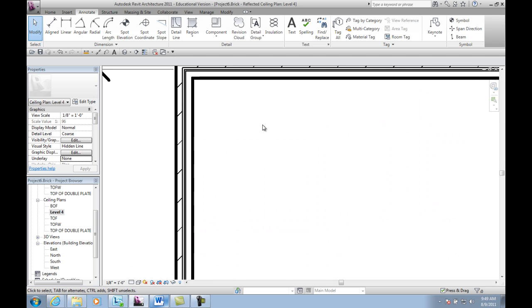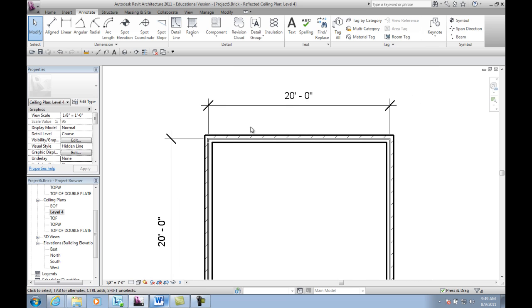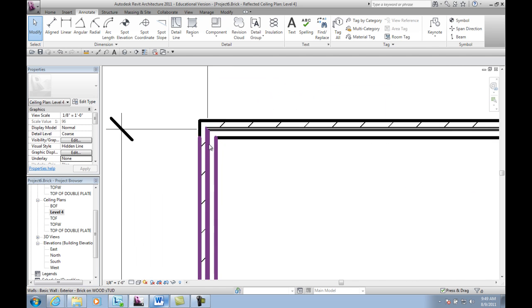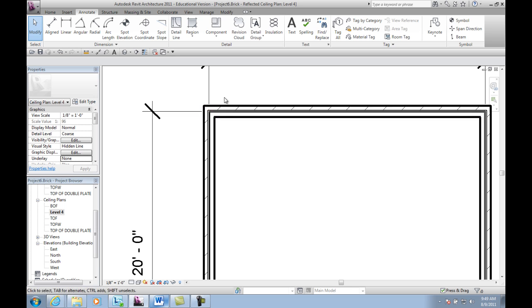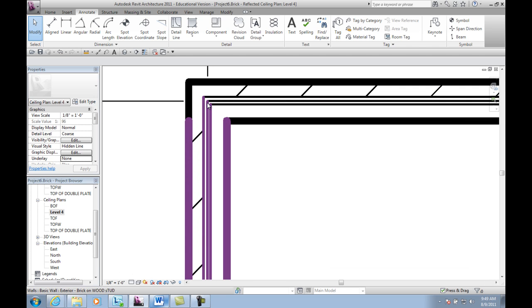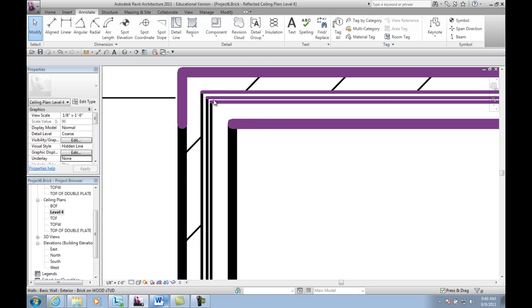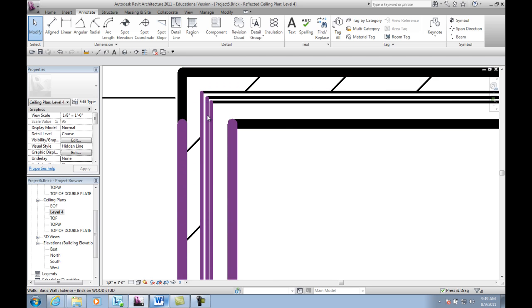Now, what you're seeing is this dimension always goes to the exterior wallboard of the load bearing structure. This is a brick veneer. It has nothing to do with load bearing, so your dimensions always go to the edge. Sometimes in prints you don't even have your brick showing on your floor plan, but this one I do. Just remember, your dimensions are always of the structural framing part of the house, and it goes to your exterior wallboard.